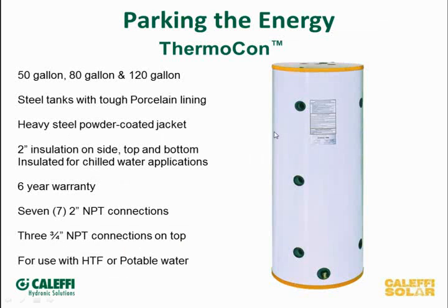We talked about the tank. There's another picture of it just showing you the different sizes that are available, and it is porcelain lined. Now, when you use it in a domestic water application, we've given you a bunch of 3/4 tappings on the top, so you can add anode rods. Into that earlier picture where I showed it connected to the desuperheater, well, that would be a tank holding domestic water, then potable water, so you'd want to drop some anode rods in it there.